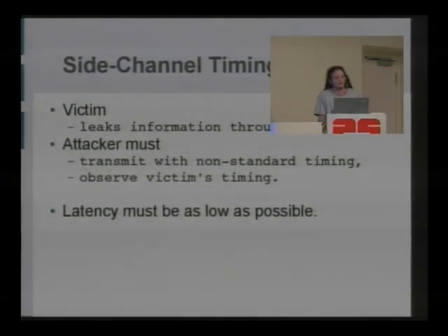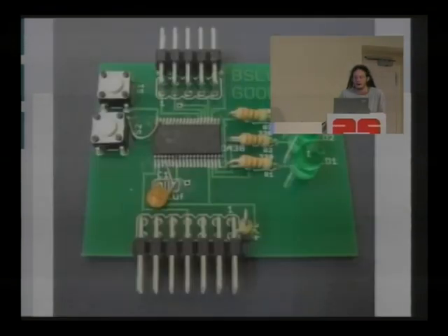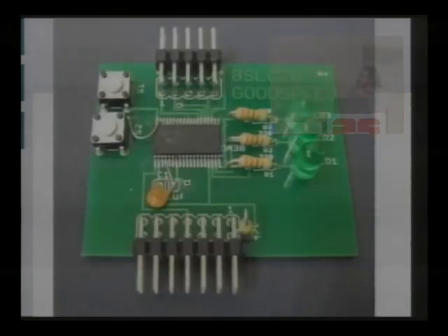If there's a context switch caused by the preemptive multitasking of your PC, then PC software that's trying to bitbang this will fail. On a microcontroller, you have no such interferences. You can write an application that runs on the board and behaves exactly as you instruct it with no operating system to get in the way. This is the second generation of the password cracker.